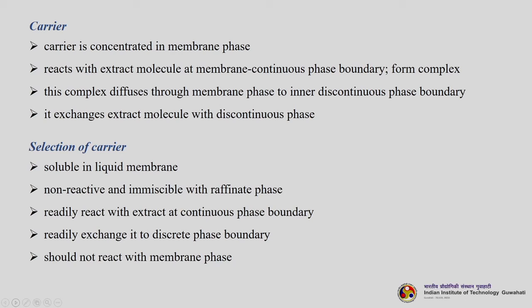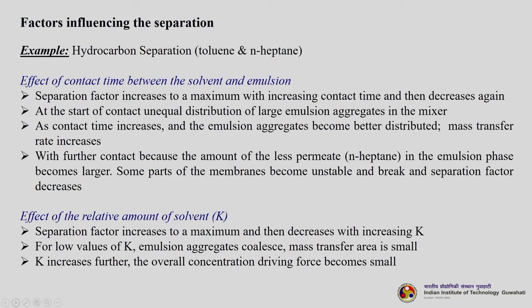Now it should be soluble in the liquid membrane, it should be non-reactive and immiscible with raffinate phase, okay, or your extract phase. Otherwise it will try to dissolve or get inside the extract phase. It should readily react with the extract at continuous phase boundary, readily exchange it to the discrete phase boundary, and should not react with the membrane phase. So these are some of the properties of the carrier which need to be taken into account when you are choosing a carrier. Now, factors influencing the separation.